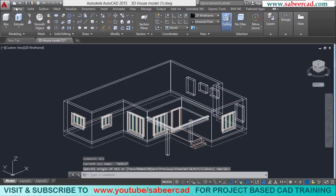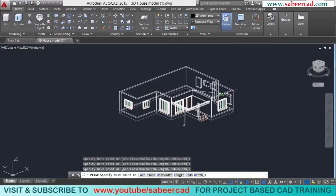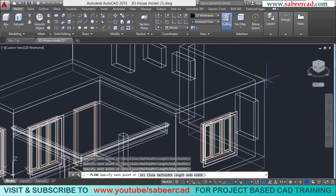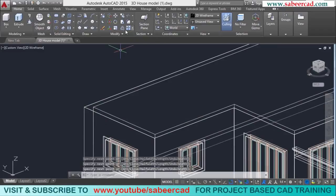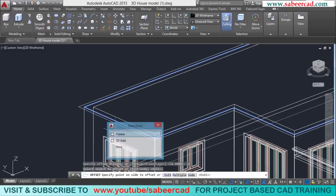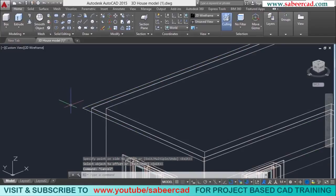When you give an enter, it will go back to the world coordinate setup. Next, I'll use polyline command and I'll sketch the boundary. So I'll pick the various corner points in the top of the roof. Then I'll close to complete the polyline. Next, I'll go to offset command and I'll offset this polyline through a distance of 15 centimeter. So I'll give 15 and this is the object to offset, which is the polyline, and I'll pick a point outward. Now it is offsetted outward.